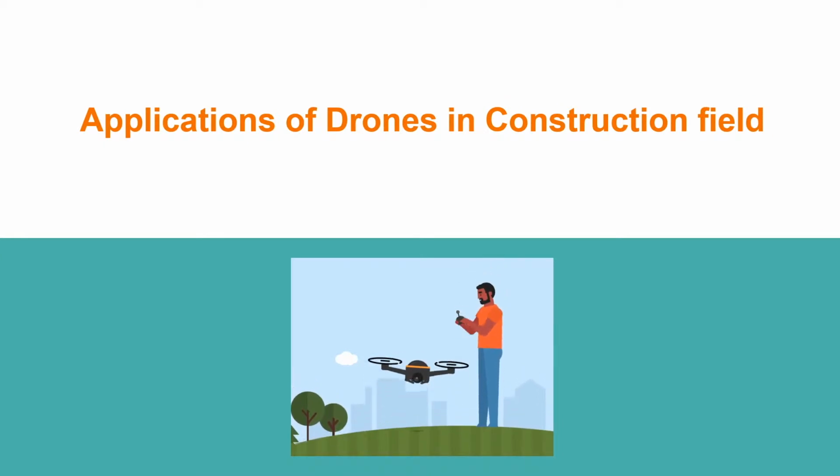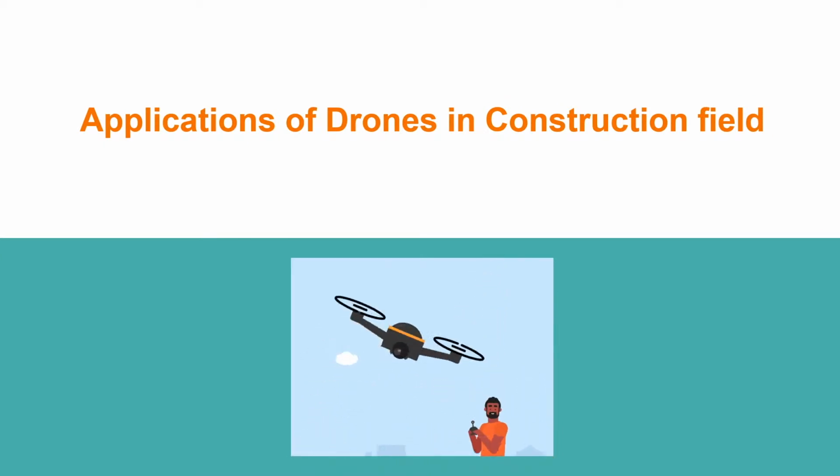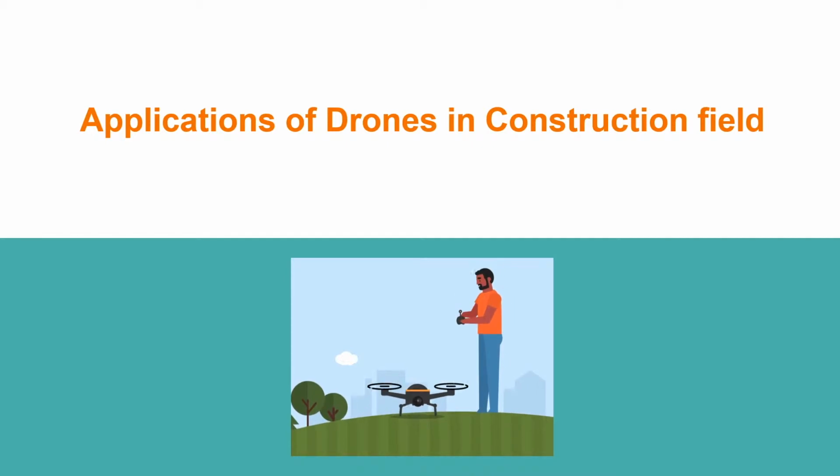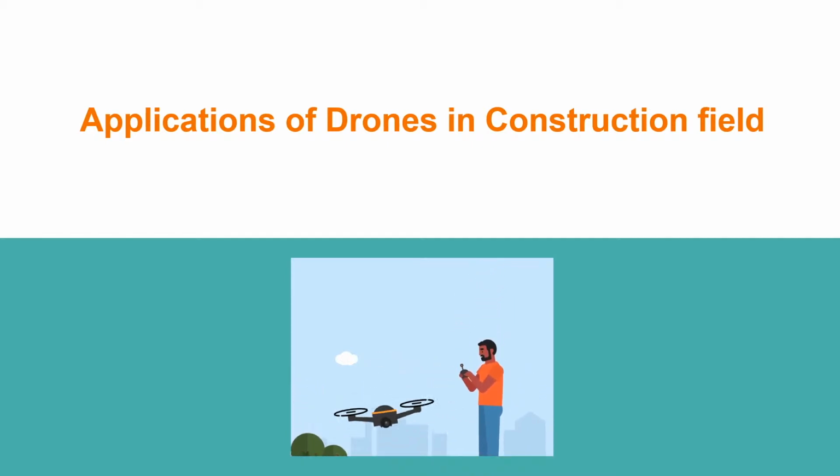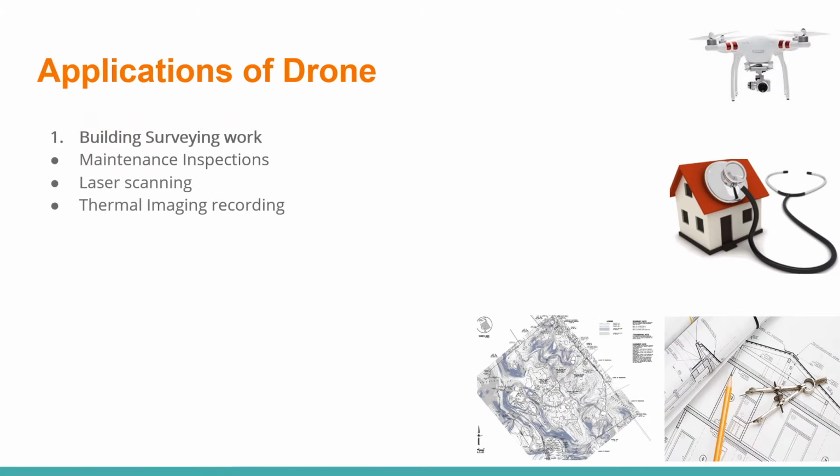Drones is one of the new technologies in the construction field, and I'm going to introduce 3 major drone applications in the following slides. Firstly, it could conduct building surveying works by its camera installed in the drone. For example, it can carry out maintenance inspections by laser scanning and thermal imaging to detect building defects.